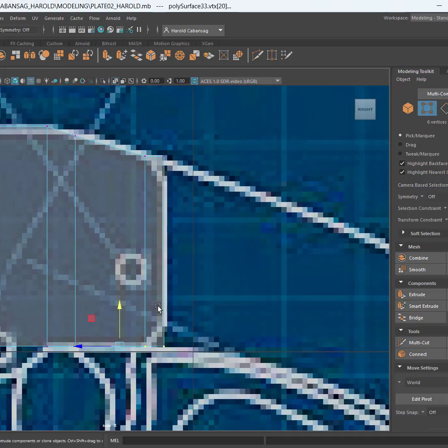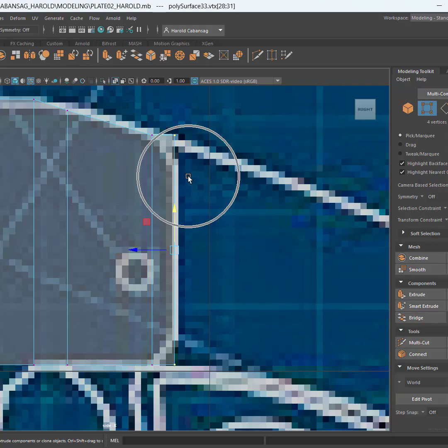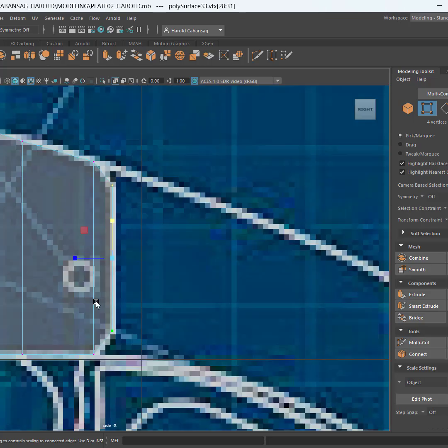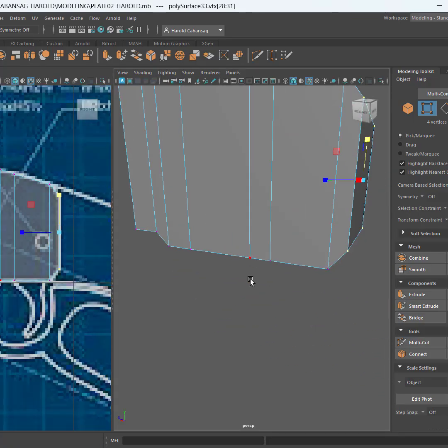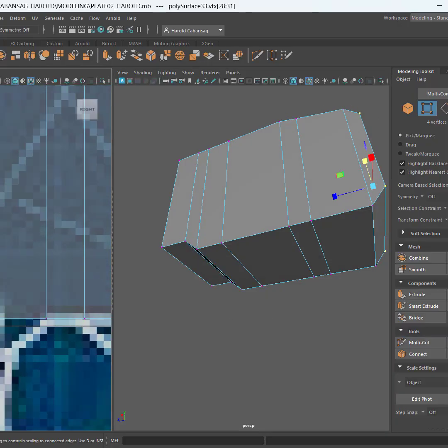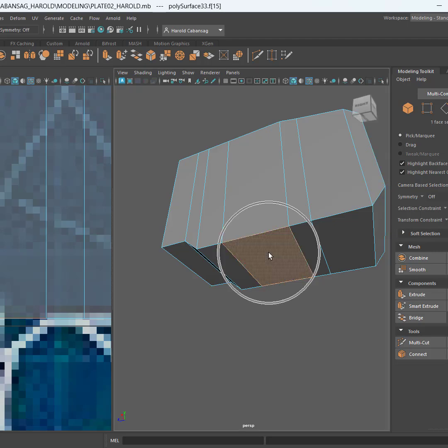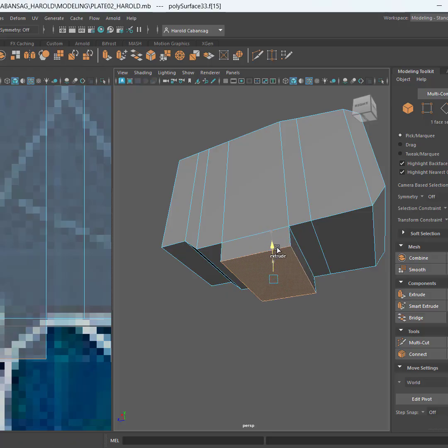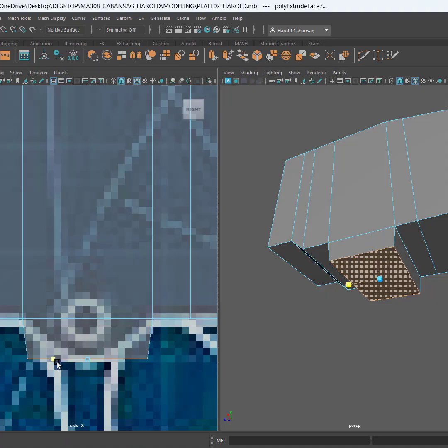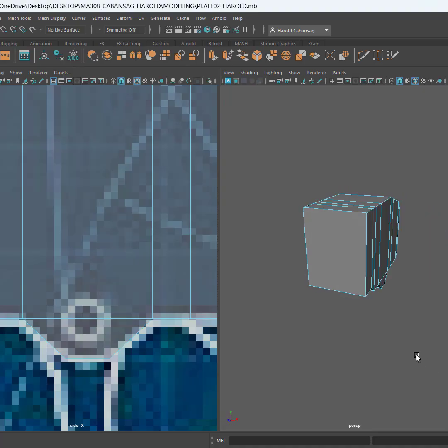But for vertices such as this, with symmetrical movement, I use the scale tool so that I can pull them together there. So now I have followed the reference. This is going to be for the polygon. Q, select this. W for move tool, Shift and drag down there. And then I'll press R, scale to fit it. W for move, and there we go.